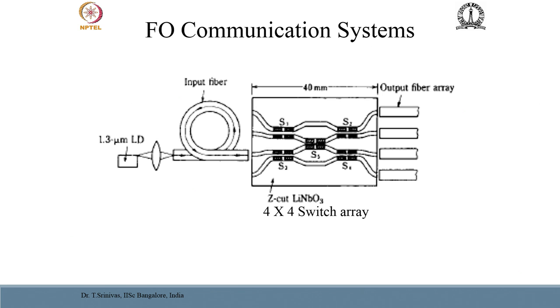This is a typical fiber optic communication, a very simple fiber optic communication link, where at a particular given node in a network you need to switch between different output ports. Let us assume there are 4 nodes to be addressed and each one operating with a different signal. So, all the signals could be addressed through optical fibers. There are 4 input ports X1, X2, X3 and X4, and the requirement is that the signal has to be routed into any of the output ports Y1, Y2, Y3, Y4. So, the specification is given in terms of a transmission matrix, for example X1 going to Y4 and X4 going to Y1 and so on and so forth.